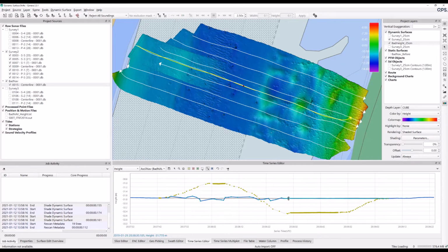Another thing you could do is you could use our sample range tool. So here I can just draw a box wherever I've got samples, and I can shift an entire section at once. So this is another great tool to use maybe when you've gone from just RTK to DGPS in one quick little stint, and you just need to adjust that one little area.